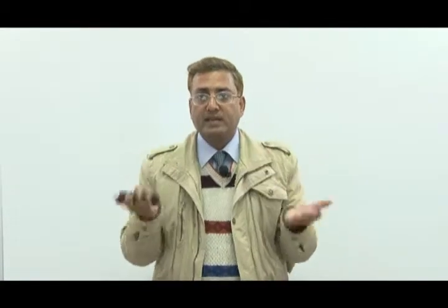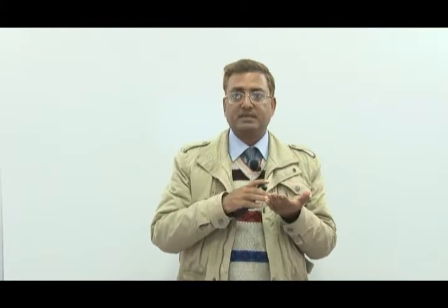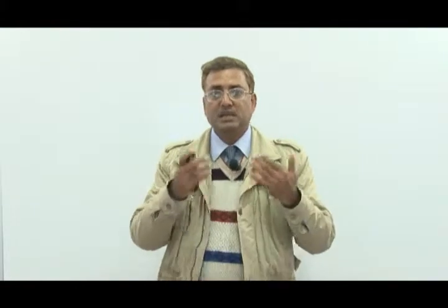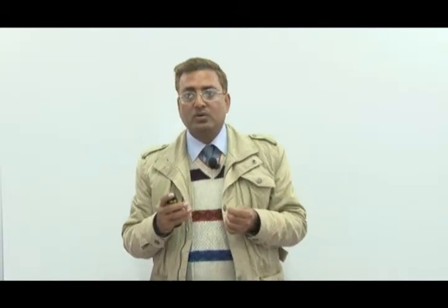So the coordinate transformation, that is mapping, as I told you, one can establish, and this mapping from the xyz coordinate to the natural coordinate system is given here. In equation number 3, x is equal to the summation over I equal to 1 to 8 of Ni xi. Similarly, y is the summation over I equal to 1 to 8 of Ni yi, and likewise for z as well. So the same shape functions are used for the displacement field as well.